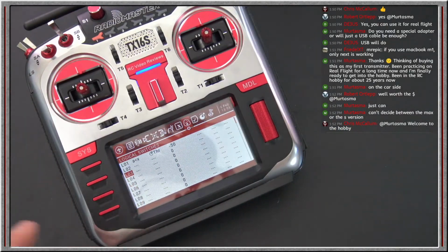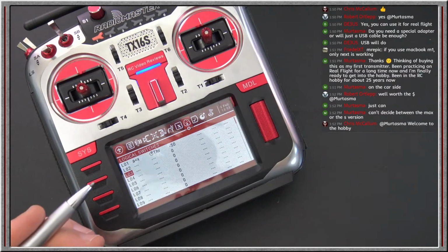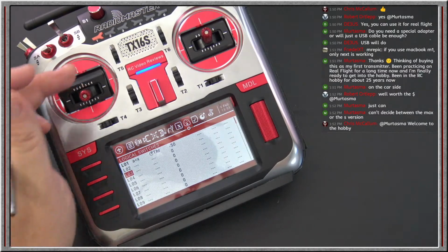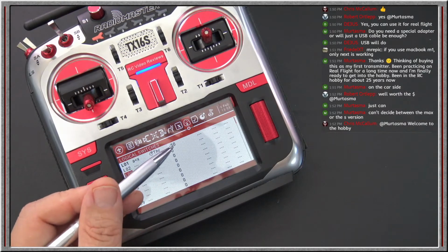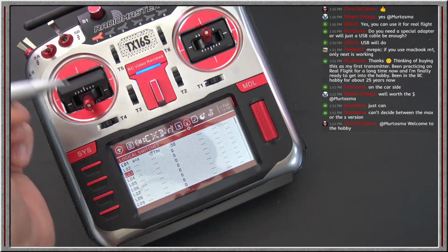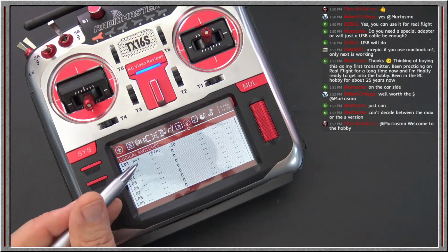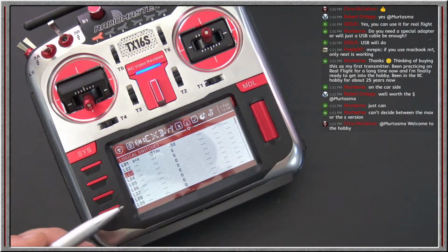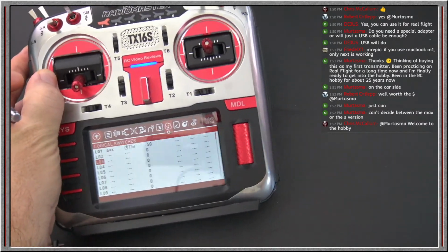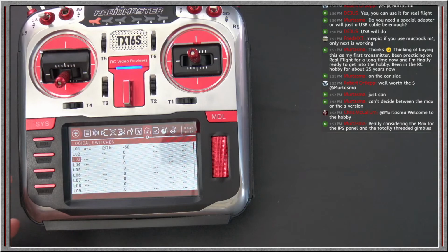Look, man, if you're going to worry about the software not working, then don't fly the radio. But if you understand the logic and say, I know that when this goes below 50%, 75% or negative 50 on the scale of 100 to negative 100, that L01 goes on, then every single time that will go on. I've never had a logical switch fail to go on when I knew the logic. So no, I don't have any safety concerns relying on logical switches. In fact, most of my configurations rely heavily on logical switches.